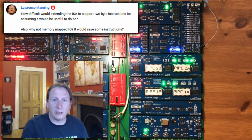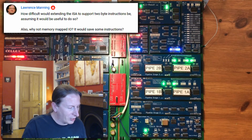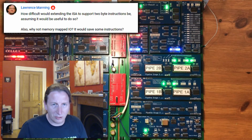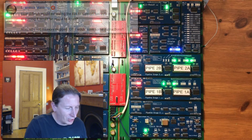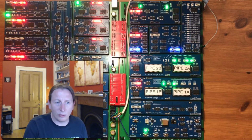So in the future, I may well consider doing a build with a wider memory data bus, and so it'll be a lot easier to do some functionality like that. It might even be possible to have a memory data bus that's wider than a single instruction, and so we can potentially get away from that bottleneck where a memory operation is a guaranteed stall in the fetch unit.